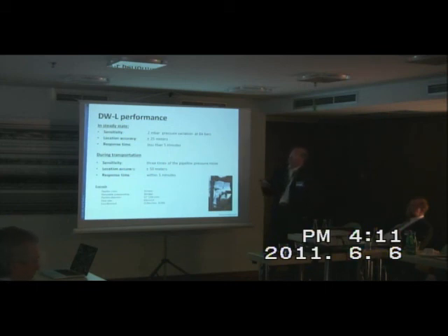The response time, of course, depends on the length of the pipeline, because we must collect data from all locations. If we have only 4 or 5 locations, the pressure wave propagation will be 1 minute, for example. For the biggest pipeline it is 2, 3, 4 minutes. It's necessary to collect all information.